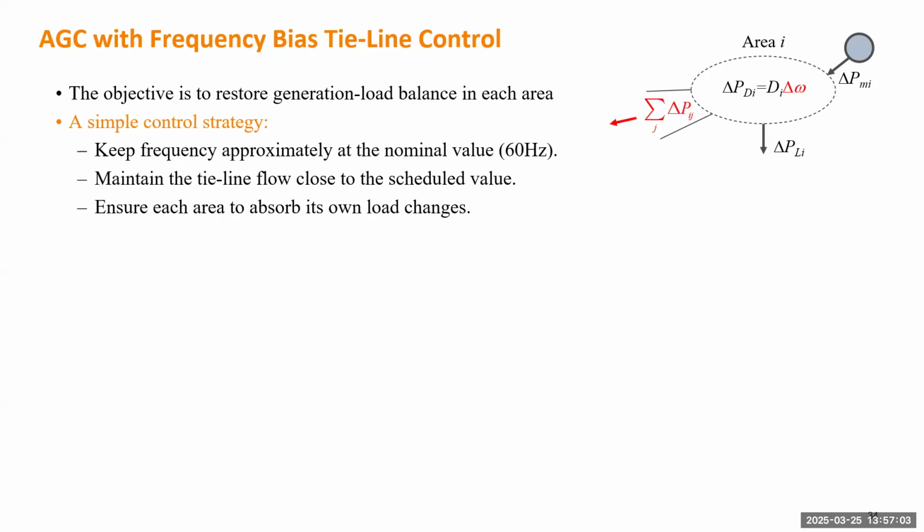Okay, so without any disturbance, we measure the tie-line flow and put all the values into the table. After any disturbance, as long as the disturbance is not large and propagating to the entire system, eventually we hope the frequency is still at 60 Hz. And when we measure the tie-line flows, each is exactly, or at least very close to, the original tie-line flow in the table.